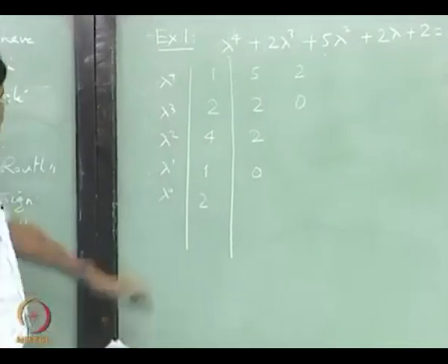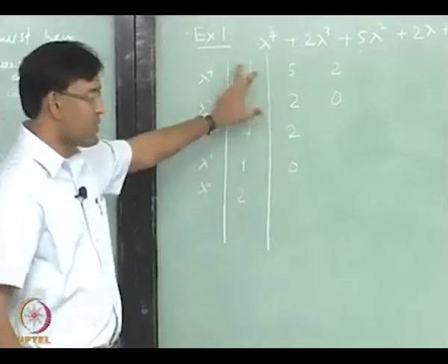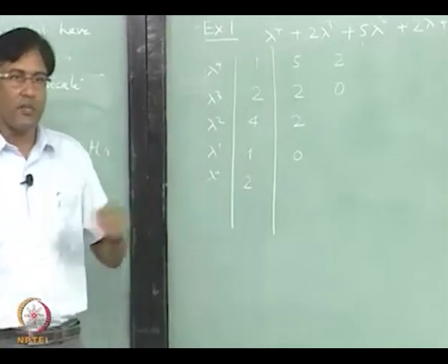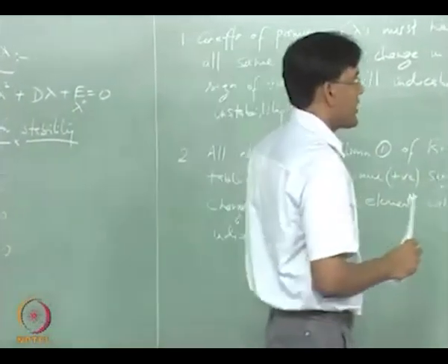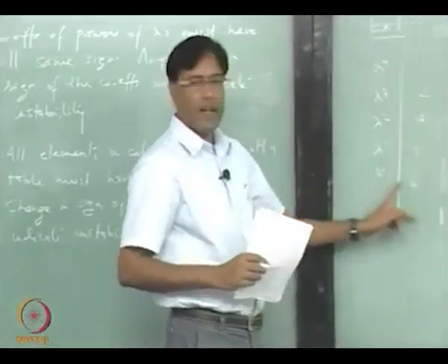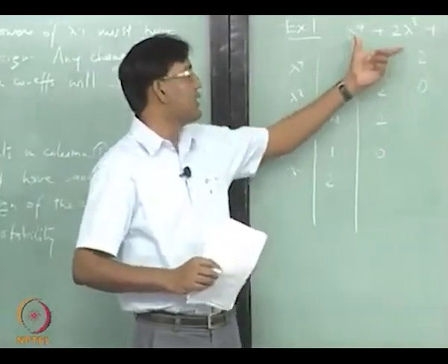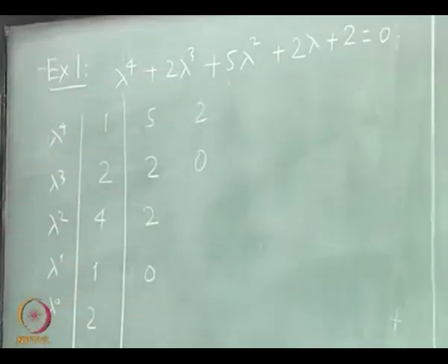Okay. So, if the elements in column 1 are all having positive sign, no, so that is the second condition that you have to satisfy. After this, what it means is the eigenvalues are going to lie in the left half complex plane, okay, all 4 eigenvalues.